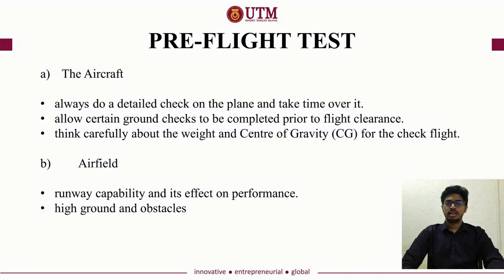The other thing is to allow certain ground checks to be completed prior to flight clearance, and we have to think carefully about the weight and center of gravity for the check flight. Expect the aircraft will inevitably be much lighter than the aircraft online. There may be no problem here, but think about it and consider speeds to be used in relation to stall speed and minimum control speed.